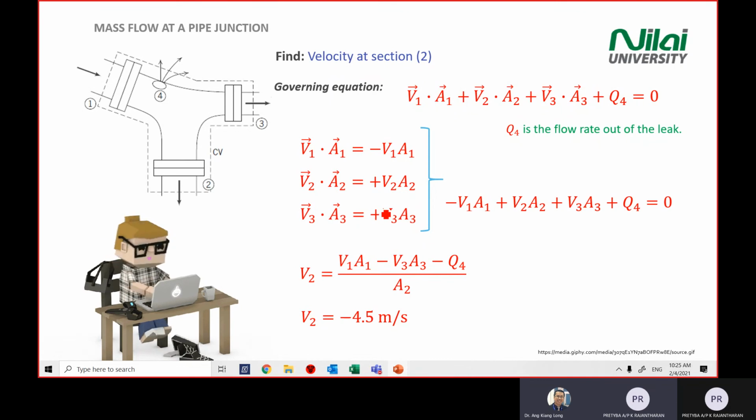All right. So later on, what might happen in your test is, for example, I ask you the value at number 2 after your simulation. From the simulation itself, let's say you get a color in the legend of the ANSYS, you'll see there's a velocity chart here, and then you can check what is the velocity at point number 2.